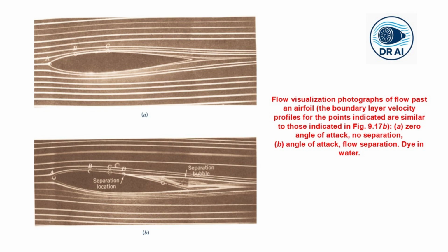The boundary layer separates from the upper surface, creating a massive wake of recirculating flow. Lift drops dramatically and drag increases sharply. So this is why stall is dangerous, especially during takeoff and landing when aircraft are close to the ground. This loss of lift can be catastrophic if there is no altitude to recover.